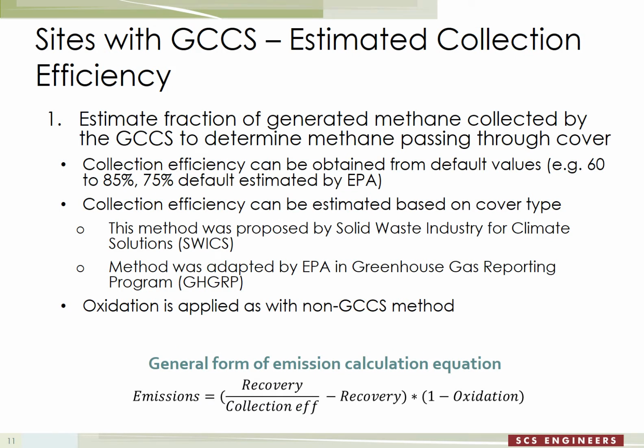There is a way to also estimate methane emissions without using the model. In this case, we make an estimate of the collection efficiency of the gas system, and you combine that with the actual amount of gas recovery and use that to predict the residual amount of gas emissions. Those collection efficiency values can be obtained from default values from regulatory agencies, or they can be estimated.